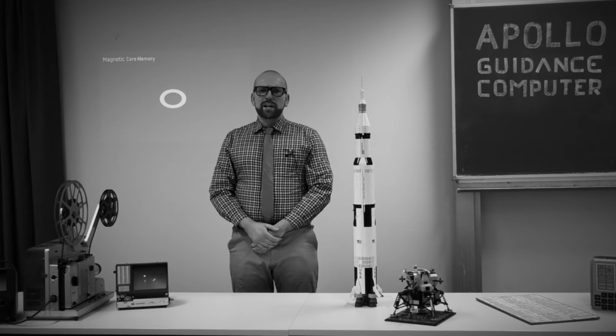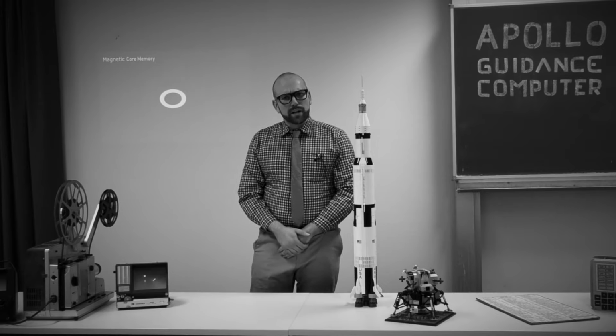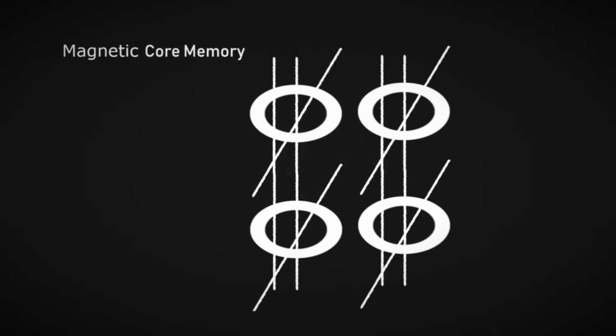Now that we know how to write and read one single bit, let's take a look at how to handle multiple cores arranged in an array. As it's feasible to only address a single core at once, it's sufficient to use only one sense line for the whole array, which is weaved diagonally through the array.